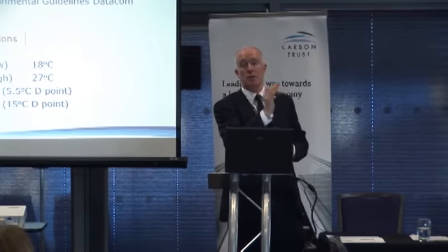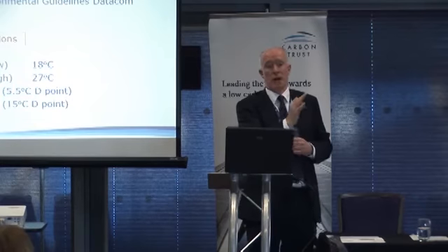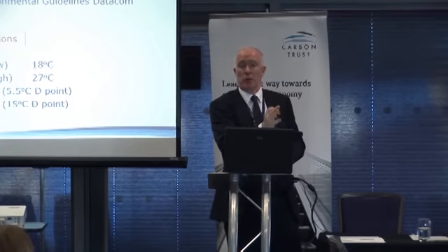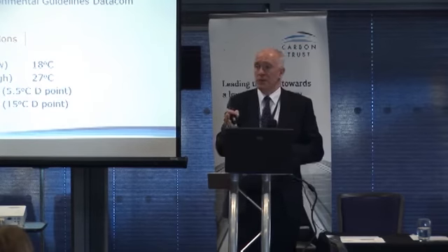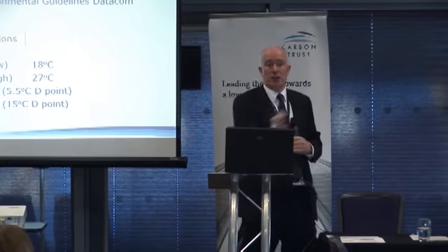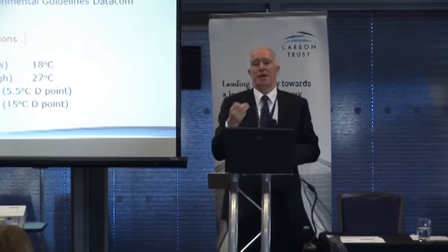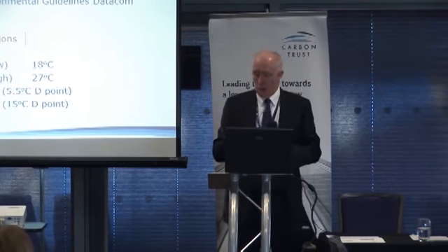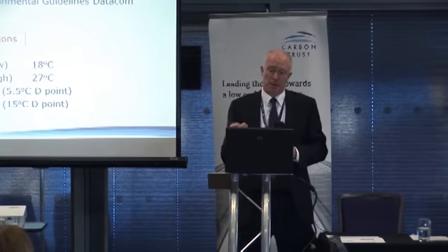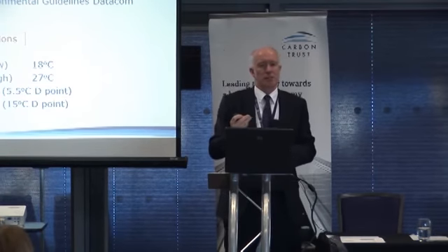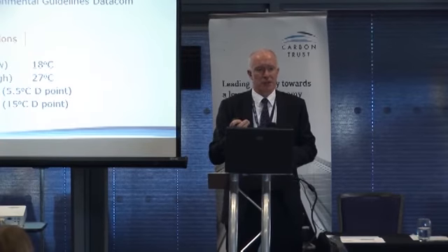At the back of the unit, the air will be thrown out, and that is waste or useful heat, whichever way you want to look at it. That is not of interest to us at all. That might be up at 30 degrees centigrade because of heat gain. That's absolutely fine. It's gone through the system. What we need is stable on temperature. And so, really important, we're talking about air inlet conditions, and that is something that is quite confusing, and IT managers often don't fully understand.